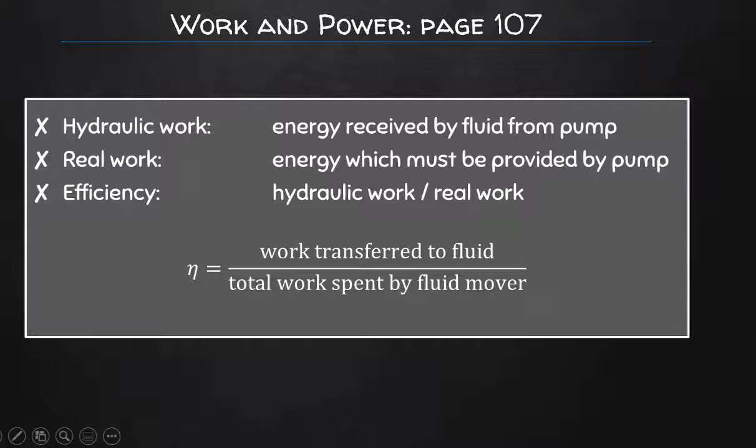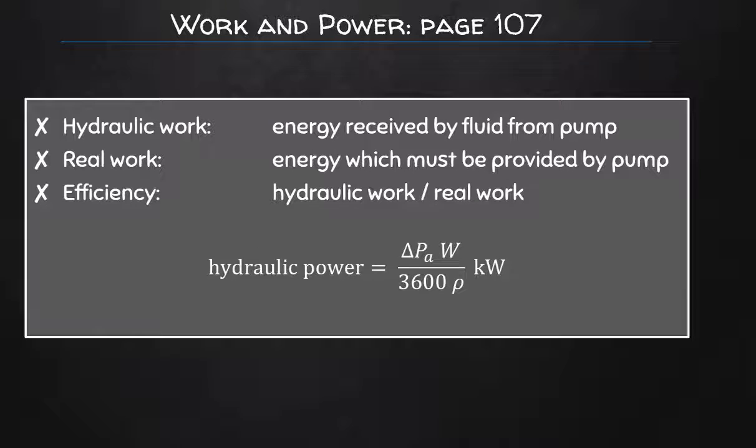Okay, the total work that is delivered to the pump is easy to determine from the electric readings that can be obtained during the pump's operation. You just measure how much electricity you're putting into the pump, or how much electricity the pump is utilizing. The hydraulic energy is computed using the following equation, which uses the mass flow rate of the system.